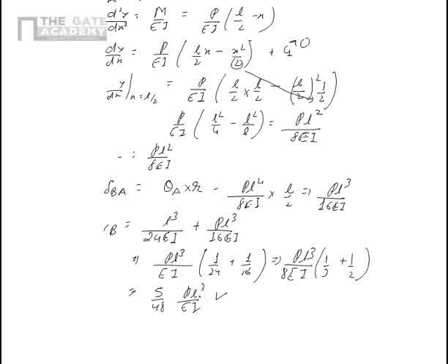Now, what happens because of the slope? See, slope causes the rotation, and this problem is relatively simple right now because we are applying the force at the center, but the force can be applied anywhere through the length. So we have to be very careful that we get the deflection only till that point where the force is applied using the bending moment formula. Beyond that, we have to get the deflection by multiplying the slope and the radius.